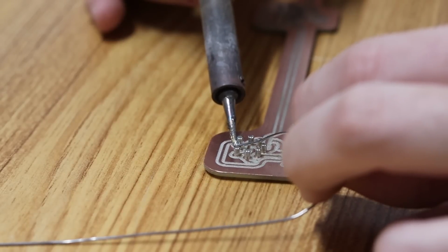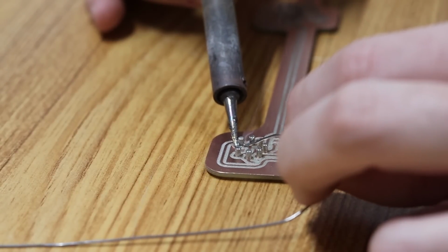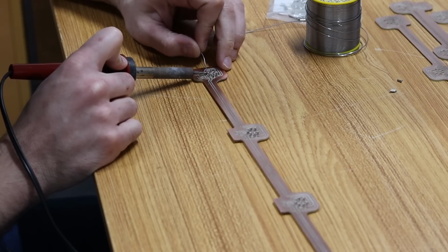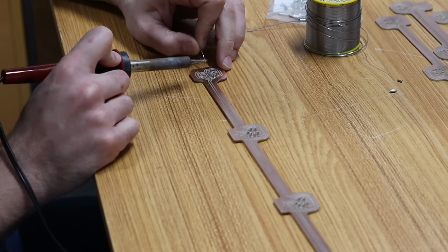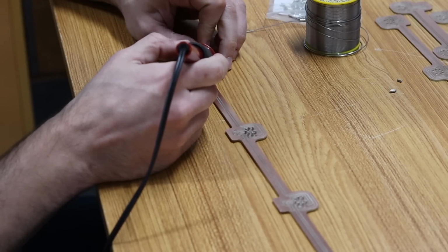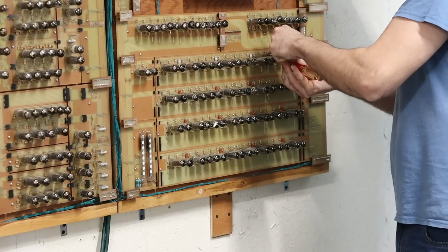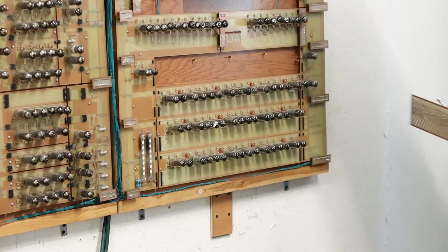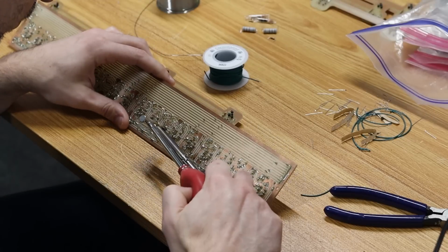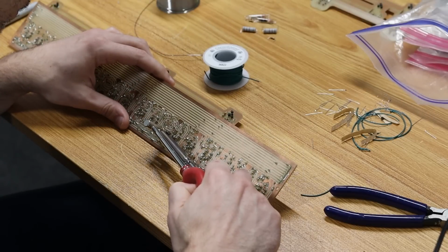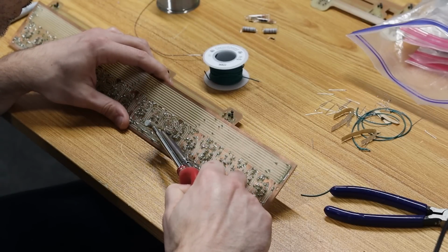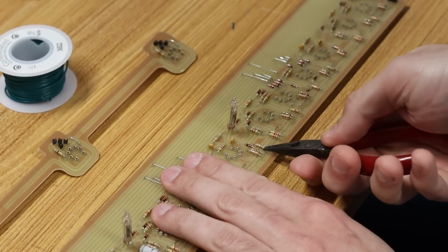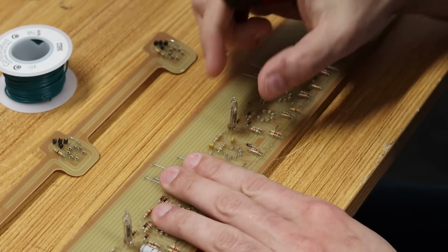If a bodge is going to be obvious or on the front of the boards, this is my go-to solution usually. A daughter board totally looks the part and is often more reliable in the long term than stringing wires around. And speaking of those memory boards, let's go ahead and pull all of them out. And I'll need to do a bit of desoldering, which on a single-sided PCB with no solder mask is extremely easy to do.